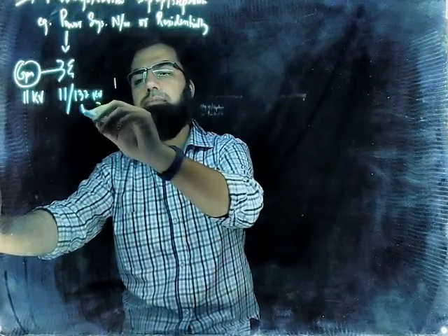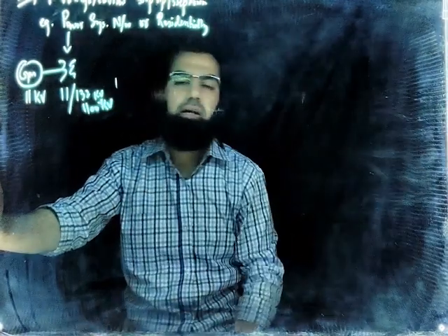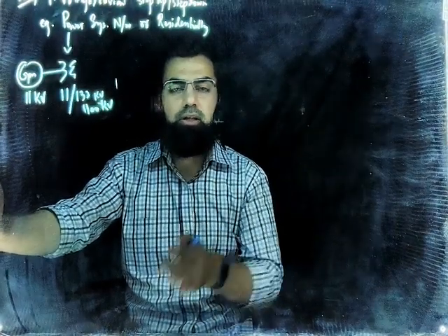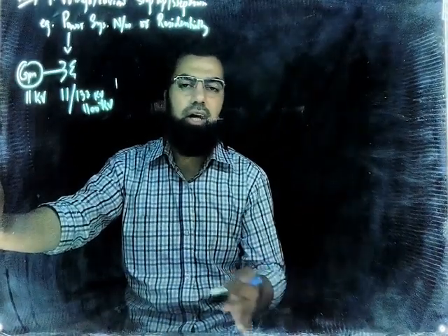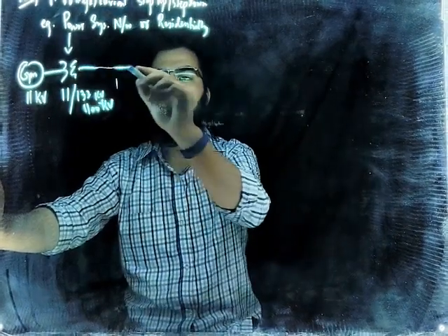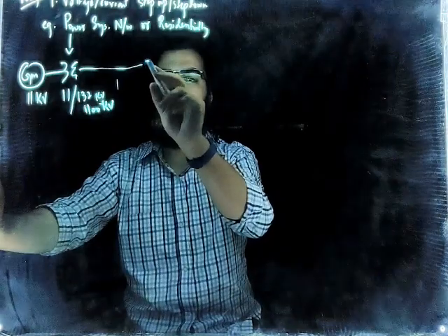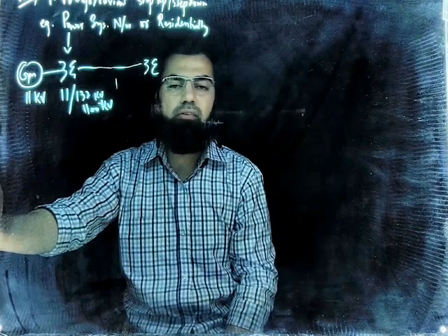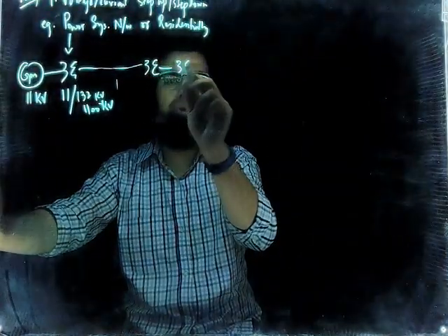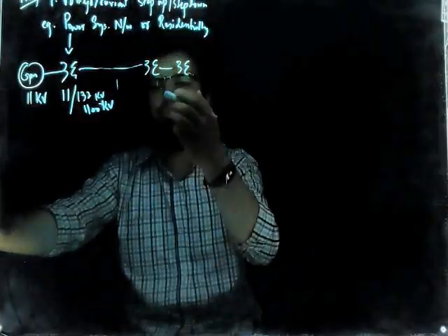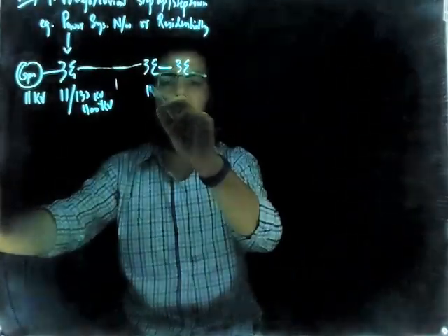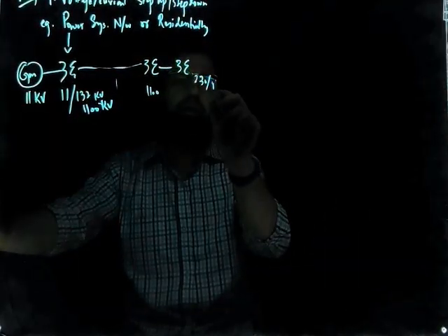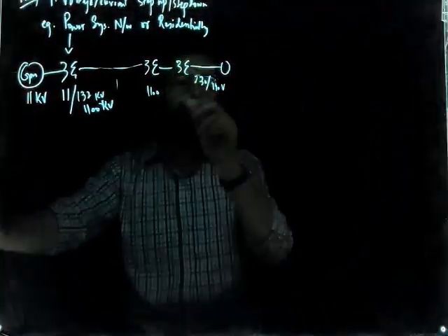We can step up this voltage. Now, why do we step up this voltage? Because if we step up the voltage, the current will decrease. If the current decreases, I square R losses in the system will decrease. We can then transmit this voltage over a long distance, and at the distribution side, because the consumers cannot directly consume 1100 kV, using a series of transformers, substations, distribution transformers, this voltage is subsequently reduced from 1100 kV to 230 volts or 440 volts, that goes to residential purposes.